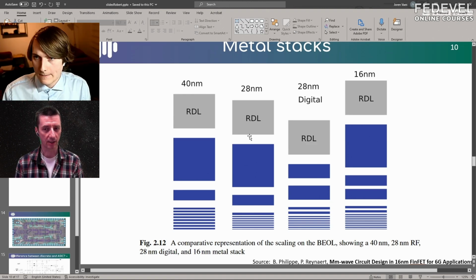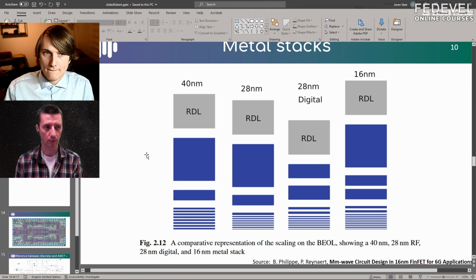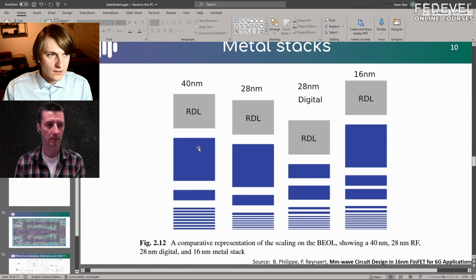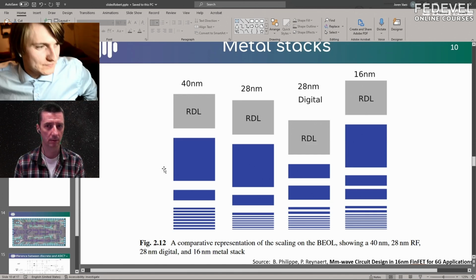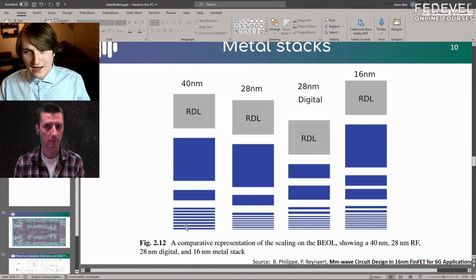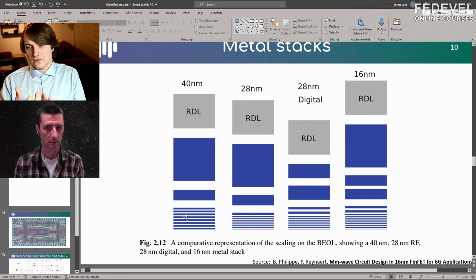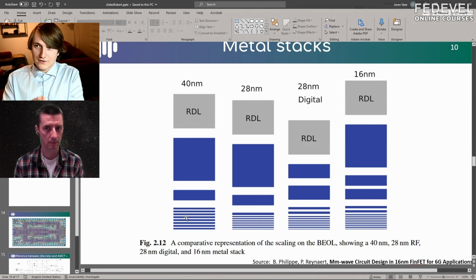They do it intentionally thicker because they would like to use higher currents? Yes, because this is actually one of the problems you have in chips: because your wires are so thin, you have what they call electromigration. The current flows through a wire, and the current flow is actually electrons, right, moving through your wire from the negative to the positive terminal. And while they're flowing around, they bump into atoms. And every time they bump into an atom, they move the atom a bit.